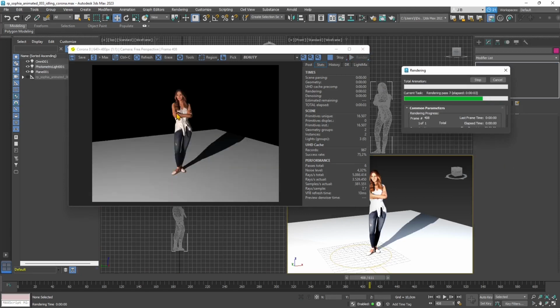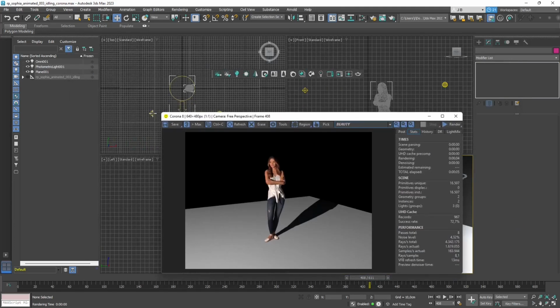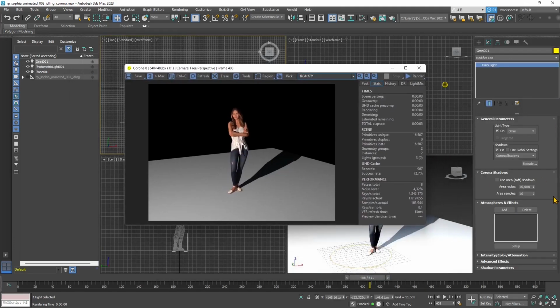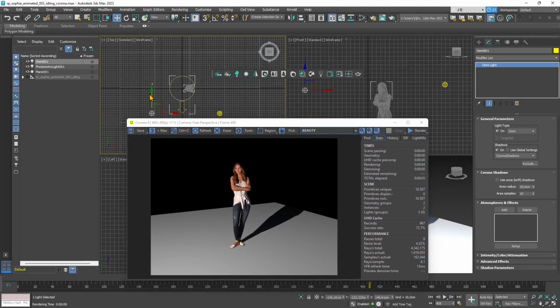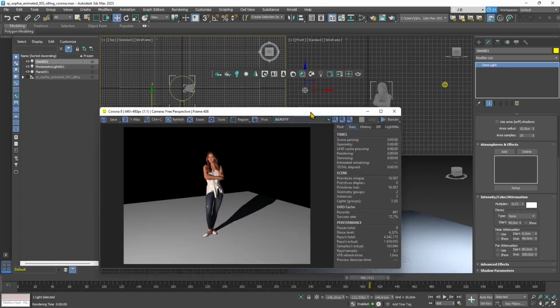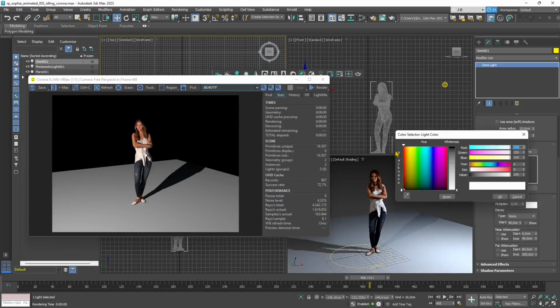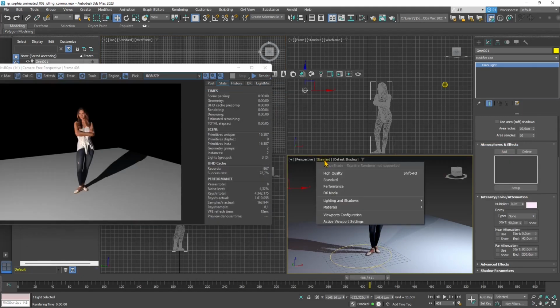Now you can see the Omni light, the standard Omni light, it's more intense than the photometric, because photometric are more realistic, while Omni light is more kind of an approximation of what an Omni light could be in reality. So let's say photometric are more accurate in terms of realism and in terms of physical effect.